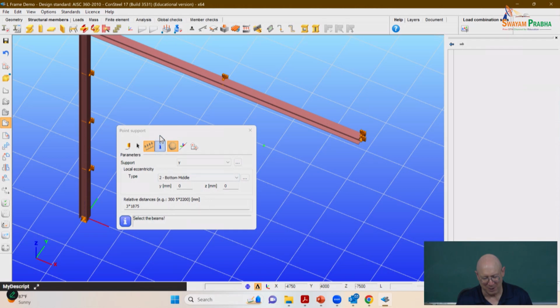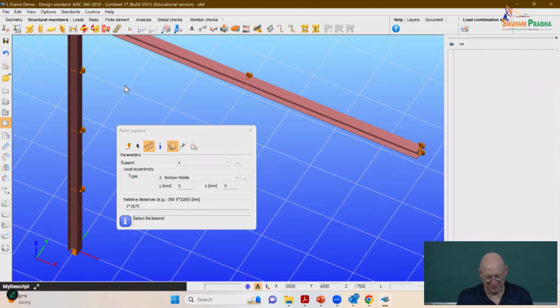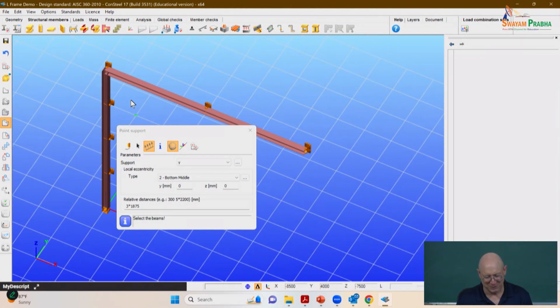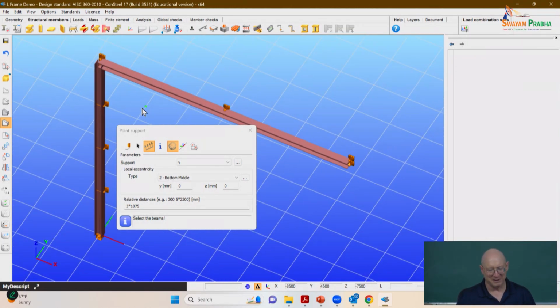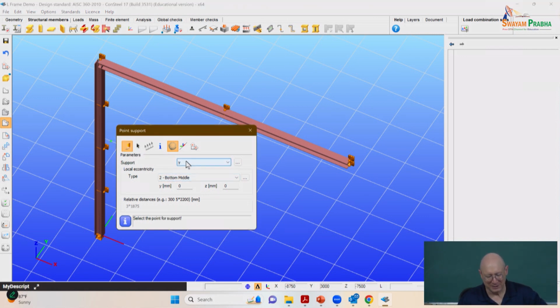All right, now if you think about what we've got here, we should have kind of the supports we would need. It kind of represents a physical structure. Except I've forgotten at this point that I better support the right-hand end of the beam in the plane of the structure. And so I need another point support.